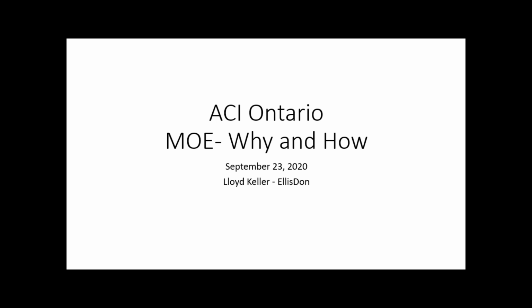Again, my talk is MOE: why and how, and MOE is obviously modulus of elasticity. Hardened properties for concrete have typically been mostly limited to compressive strength, air void spacing, and RCP ratings. Other properties that are more regularly tested include shrinkage and ASR reactivity. Properties like modulus of elasticity have been much less called for in the materials testing program. A reliance upon its values being a function of compressive strength or empirical has until now been much more the norm. This appears to be changing, and now engineers are much more requesting that these properties be measured.